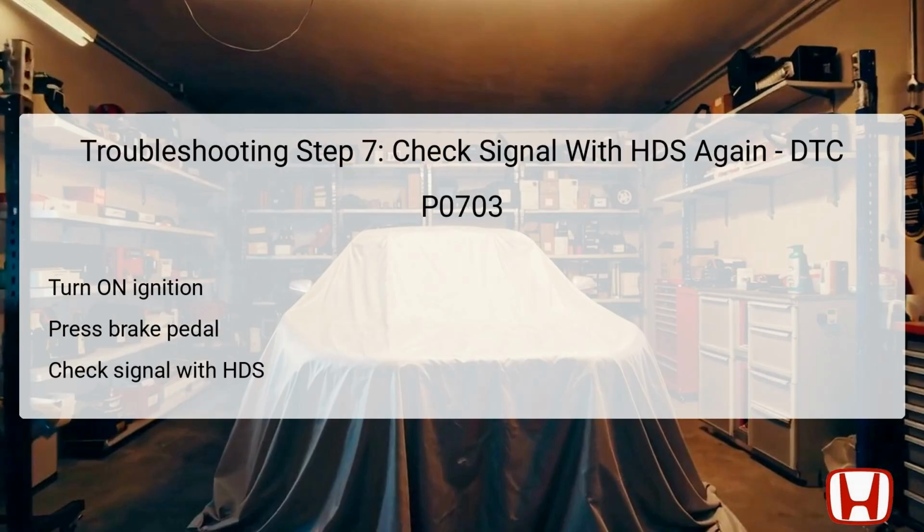The seventh troubleshooting step involves checking the brake pedal position switch signal again using the Honda Diagnostic System, HDS. Start by turning the vehicle ignition to the on mode. Once powered on, press the brake pedal, as this is necessary to check the switch functionality accurately. At this point, the parameters will again need to be assessed using the HDS. This is crucial as it can reveal whether the issue is intermittent.